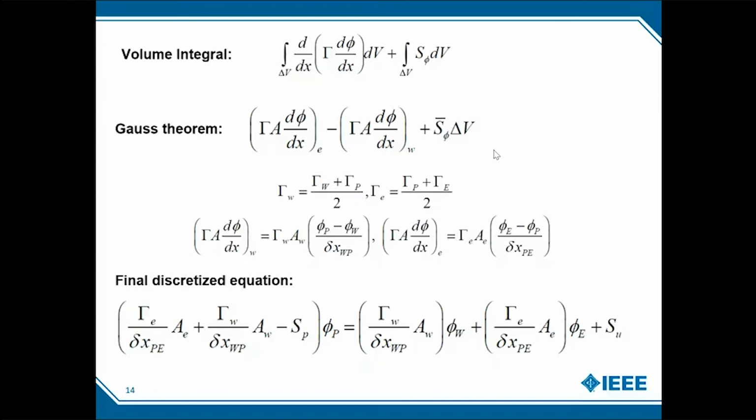So, for validation, there are different methods to do it. One of the best ways to validate is if someone has done experiments on a similar problem. For validation, you need a base solution that already exists. If you read any research papers, there are multiple validations done. The best ones are against an experiment that was done initially, or other cases.